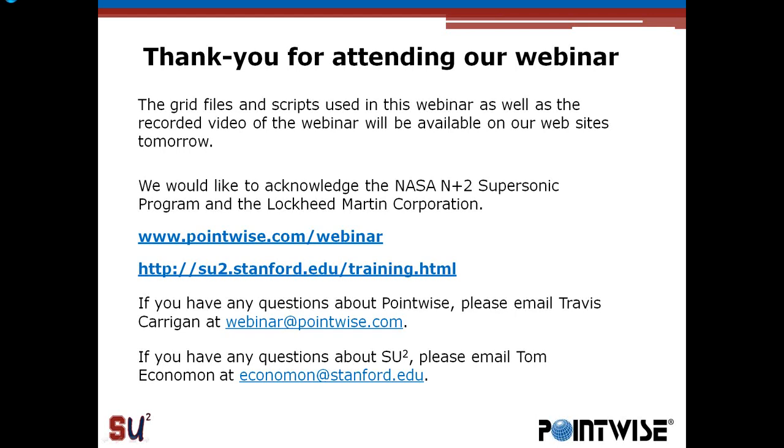Do you experience any fluctuations in the sectional pressure coefficient for the shape optimization case because of lack of gradient smoothing? Pressure fluctuations. Can you read that one more time, Travis, please? Yeah, let's see. Generally speaking, we are typically experiencing fluctuation in sectional pressure coefficient for the shape optimization in case we are using the Hicks-Henne bump function because of lack of gradient smoothing. We project into the free form deformation box.